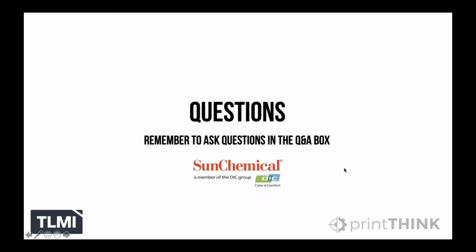Yeah, so I'm going to let Dave Bureau answer that. Dave? Hi, this is David. For a cure for a UV white ink, we would do it by several different methods. Technically, we would look at solvent resistance initially, thumb twist, mechanical resistance, scratch resistance, tape tests and such. Those are the standard conventional methods we would use. We can also use more scientific methods like FTIR or cross-link density.